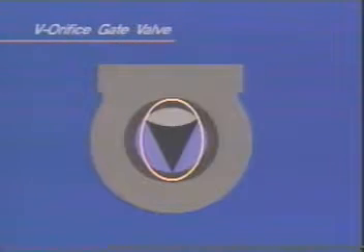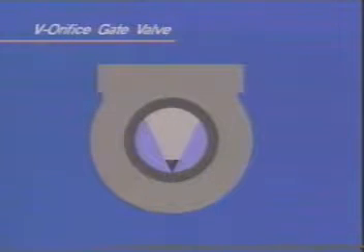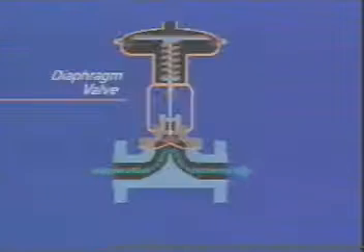The V-shaped orifice characterizes flow capacity through the valve with gate position. In many instances, the gate is a thin plate with a sharp knife edge. Knife-edge gates are often used to shear through the flow of solid materials, such as powders or granular substances. Other difficult fluids have led to the development of other valve styles.